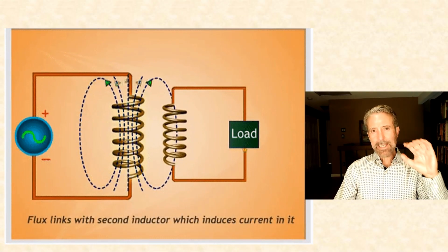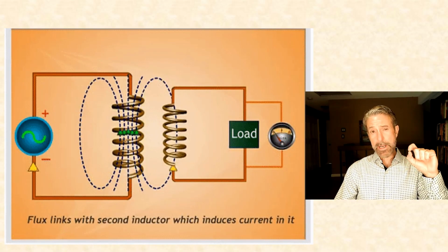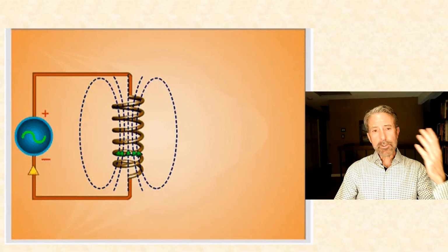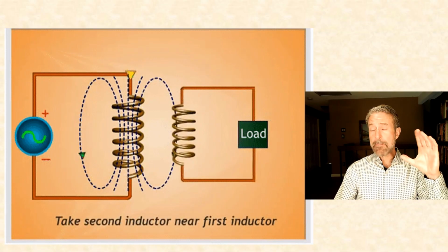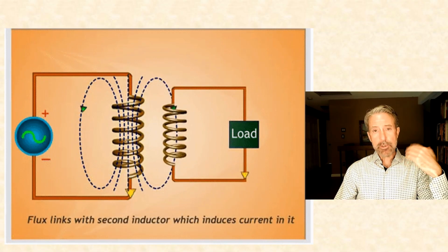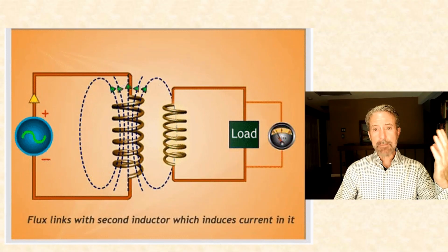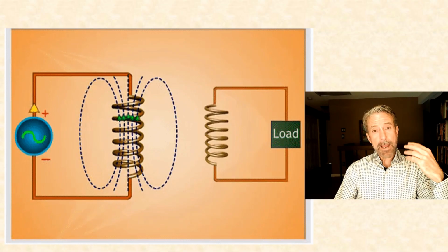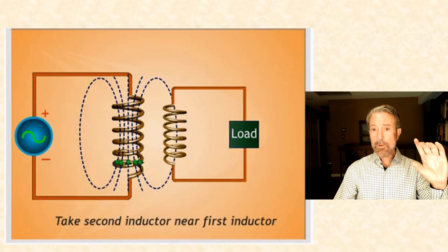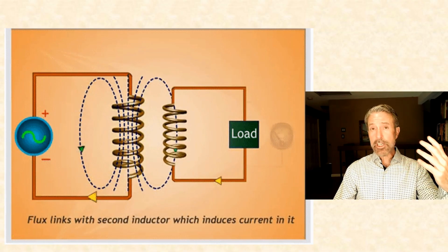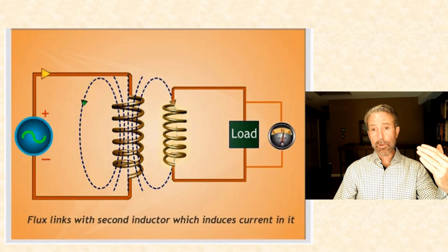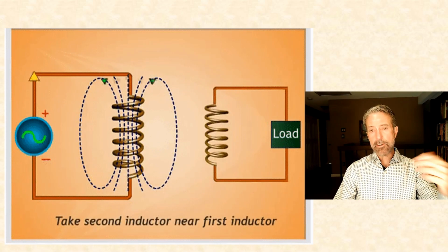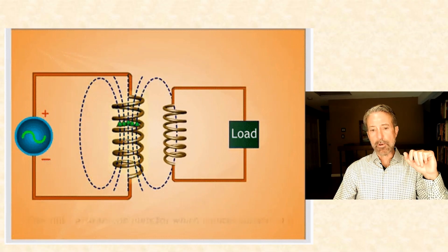This animated GIF nicely illustrates what we've stated in the flow chart, that an alternating or changing current in the powered solenoid produces a changing magnetic field in the powered solenoid, and that when a second non-powered solenoid is brought near the powered solenoid, allowing the changing magnetic field of the powered solenoid to penetrate its interior, a current gets generated or induced in the non-powered solenoid.